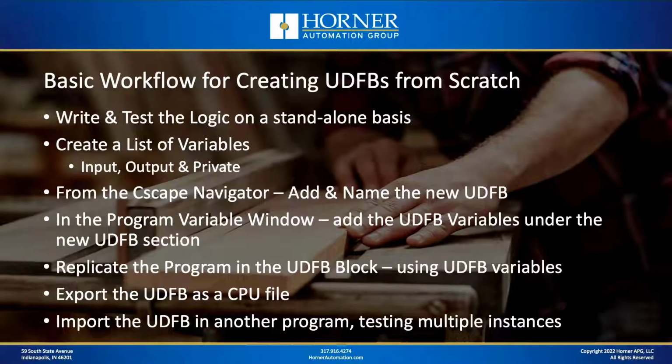Now that you've created the block and named it, now that you've added the variables to the program variable window, now you need to replicate the program that you basically created and tested in your standalone project. You're going to want to replicate that logic in the UDFB block itself, in the area allocated for its logic. Once that's complete, then you're going to export that UDFB as an independent file.